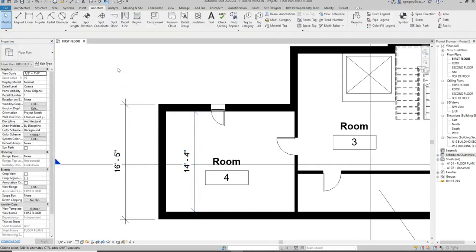It's important to understand that we don't want to have drawings on these types of drawings go to a fraction of an inch, because that is not how construction is done. But as we move into wall sections and floor plan details, we do want to refine, and so we may not get down to a 32nd of an inch, but a 1/4 of an inch or even an 1/8 of an inch may be appropriate based on what you're detailing.